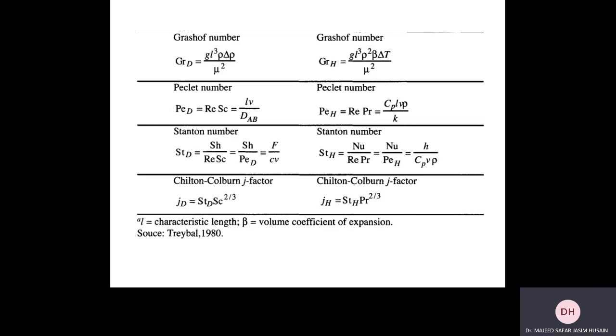And it is used to characterize fluid flow in which there are simultaneous momentum and mass transfer convection processes, since we have both of them together, the momentum, which was the ratio of the viscosity and rho, and also mass diffusivity, which was the mass diffusion coefficient. And the person who did it is called Schmidt, and he is German.